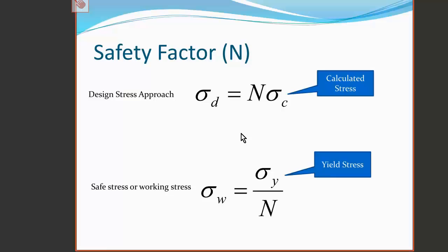So for aeronautical engineering, certain components will have different safety factors. In building designs, a typical safety factor may range from 3 to 4 for residential building construction, but for critical buildings such as a nuclear power station, we may have to build those 10 times stronger than what we expect the maximum load to be, in order to ensure safety and reduce the probability of failure due to unforeseen circumstances.